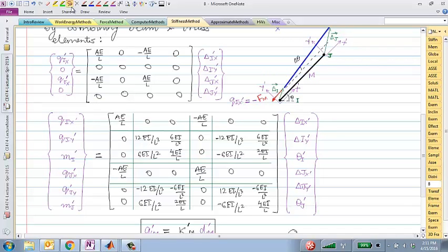If I extend it by an appreciable amount and then try to move it down, I would need more forces. Why? Because there is some tension stiffening of this structure. So that's a second order, a higher order effect, which makes the problem nonlinear and more difficult to solve. But again, we will not get into that. Most problems in most civil engineering structures, we are able to solve with these small deformations where the axial response and the bending response are decoupled.